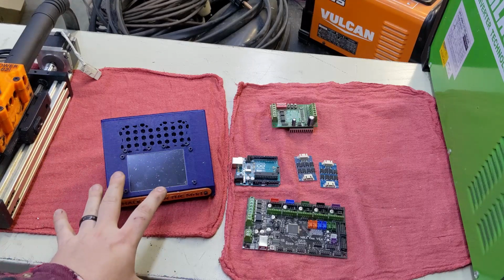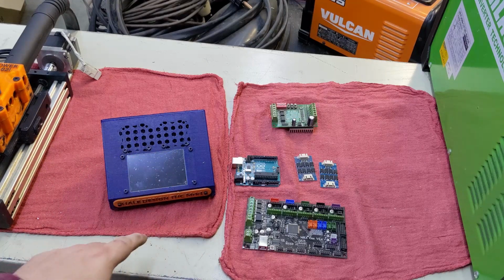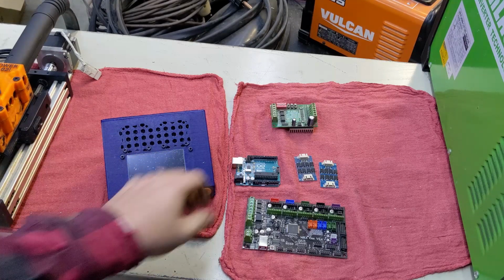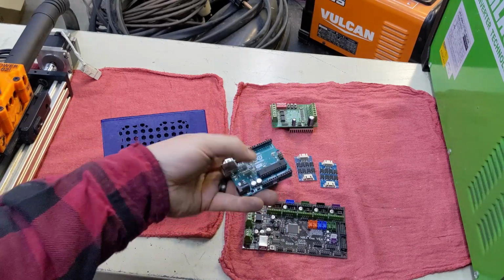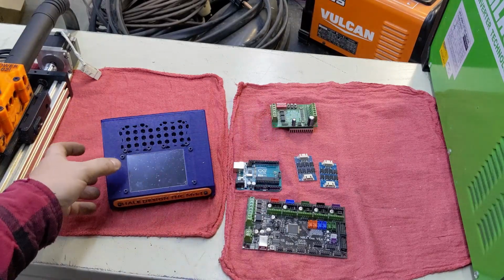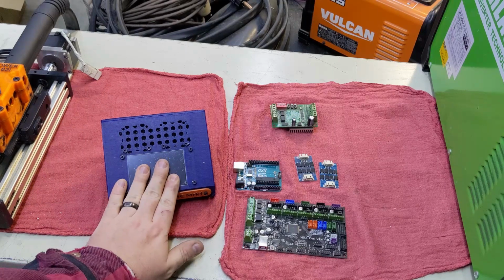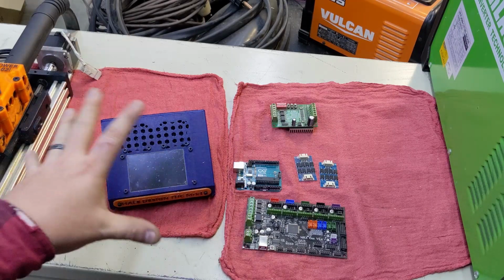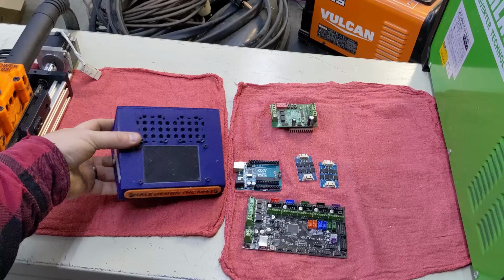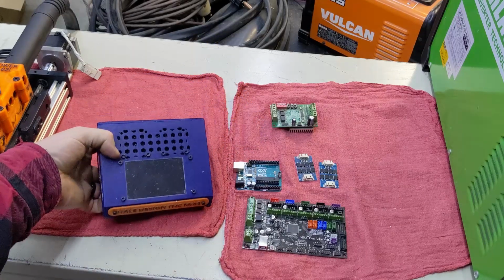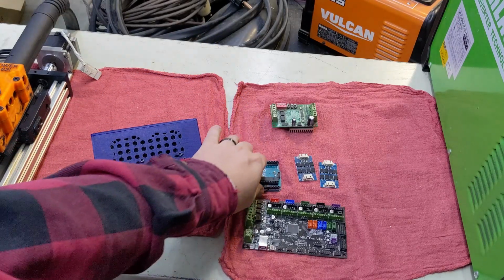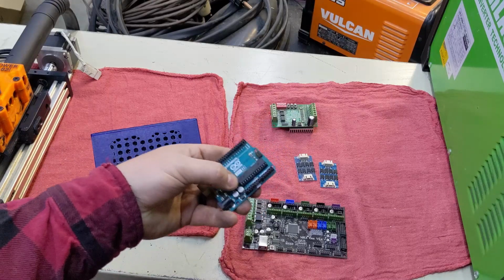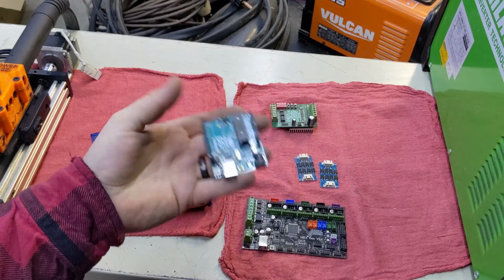Other than that, it does do the torch height calculations and move the torch beautifully. I love that part. So the Arduino does its job there. And the screen itself is not technically needed to actually use the torch controller at all. I only use it to set initial voltages, which I could literally just plug my computer in and hard code.